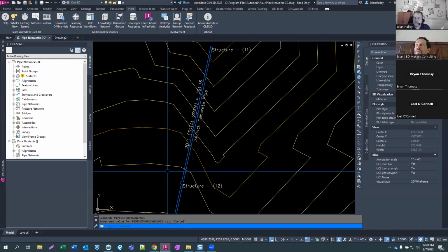Yeah, I honestly find that often in a lot of programs that they're trying to speed up, especially visual and modeling programs, where live updates all the time slow everything down, and Revit's notorious for this. You can change a whole bunch of things and the tag doesn't update, but you can move the tag and move it back, and the tag will say, oh wait, I've got to display the information from the object. In the Revit world, it's sometimes the tag, but often it's also the element. I move something and move it back, and then the tags pick up on that new data. I think this is a common theme: they realized half the reason programs are so slow is that every time somebody changes one piece of data, it has to update all the places that data is displayed. So they'll just turn that off unless you request it.